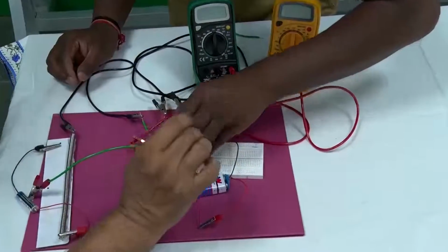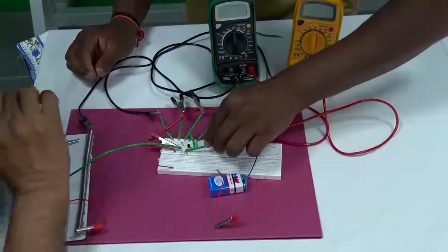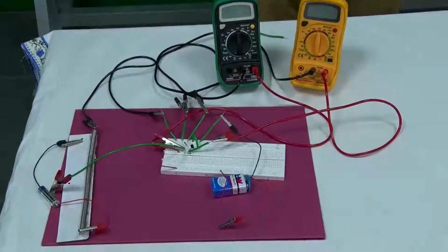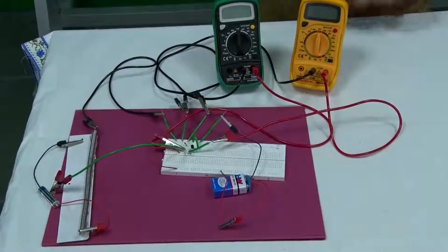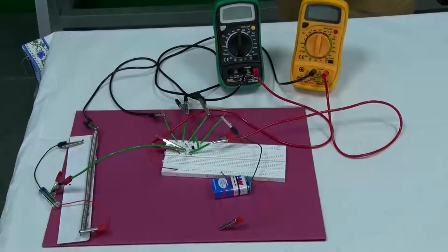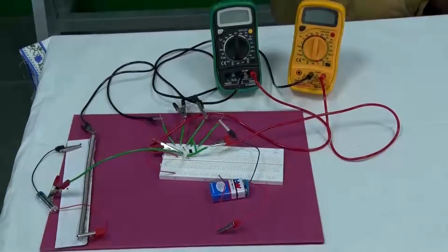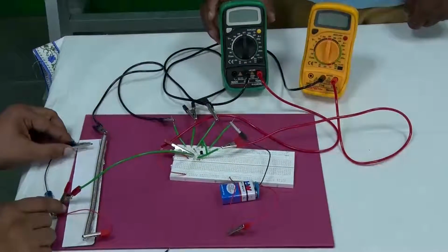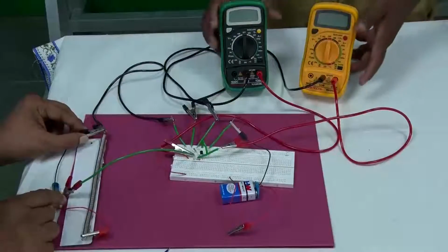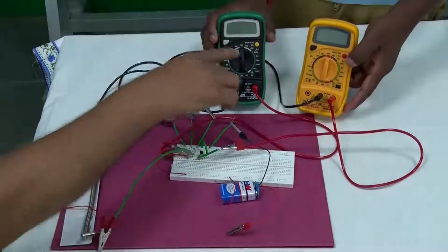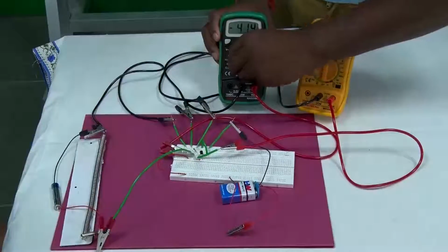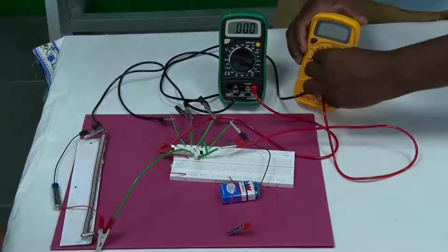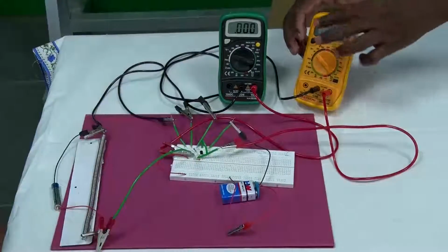And you can connect this thing here, right. So, now it is connected to the collector. Okay. So, the circuit is complete. So, let us start working on this. This 1.5 volt battery I am now connecting, all right, and I put this in the DC voltage 2 volts range, and the other one, the output, in the 20 volts range.